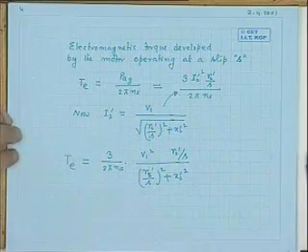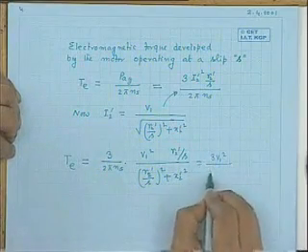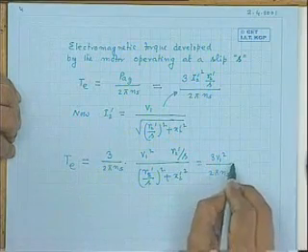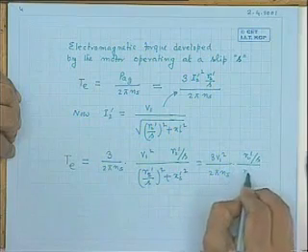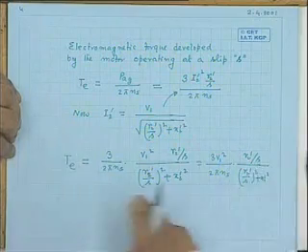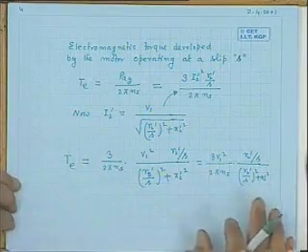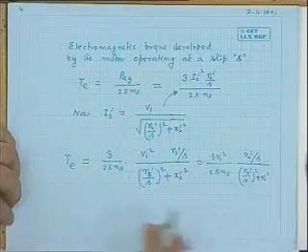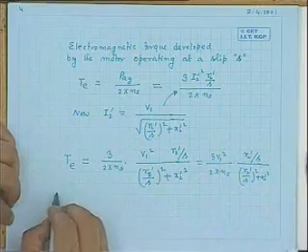This is the expression. So this will actually be 3V1 squared by 2 pi Ns into R2 dashed by S divided by R2 dashed by S whole squared plus X2 dash squared. Nothing is to be remembered, but what I am trying to tell is that your torque expression is obtained in terms of machine parameters. But in a nice form, this can be expressed. That I will do now. This expression derivation is over as such.